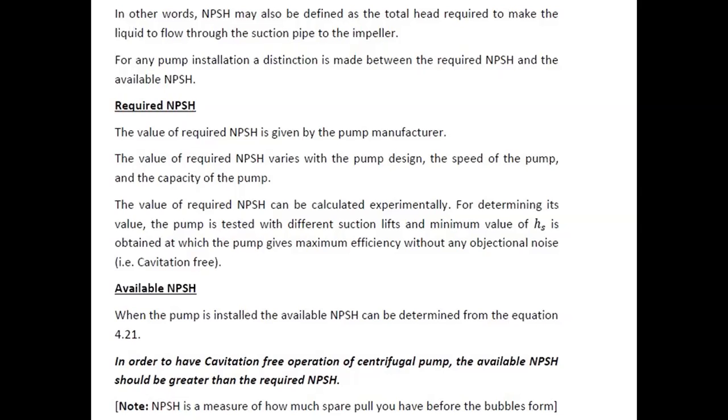Available NPSH: when the pump is installed, the available NPSH can be determined from the equation. In order to have cavitation-free operation of a centrifugal pump, the available NPSH should be greater than the required NPSH.